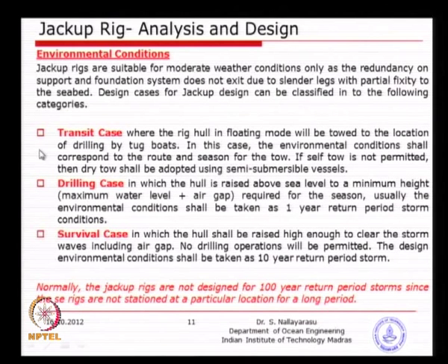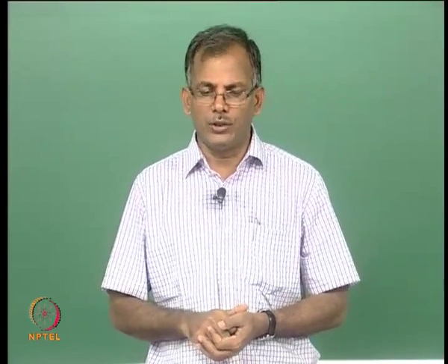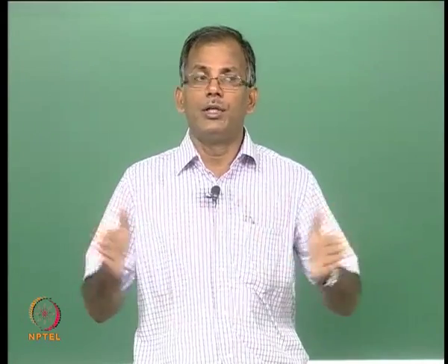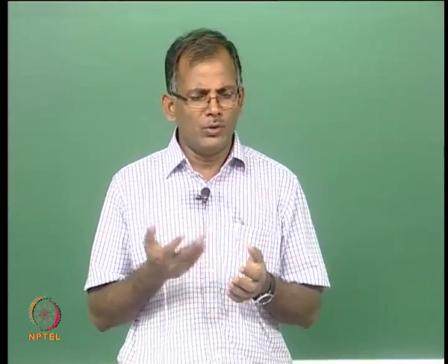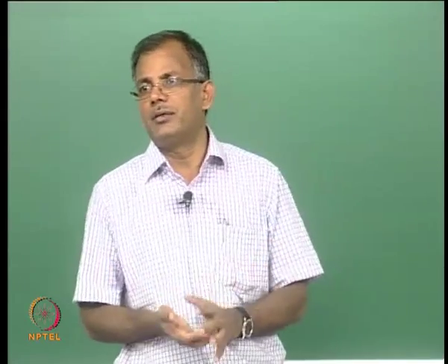So, the second one is a drilling case, wherein basically you are going to operate at a particular location and the sea conditions corresponding to that location need to be selected. But how much return period you have to select depends on how long the rig is going to be stationed there. As I mentioned earlier on, most of the time the rig will not be stationed forever. It will be 3 months, 1 year, 2 years.